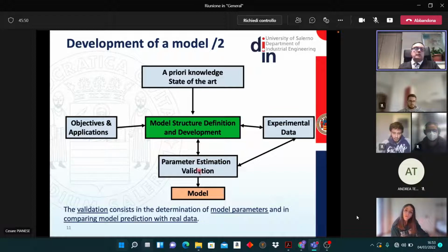But the best way would be to identify the parameters of our model. As I showed before, the shear stresses in a fluid are computed as minus the partial derivative of u with respect to y times a constant k, because we know empirically that it is true, but we don't know this k. This k in the case of blood or juice is completely different.